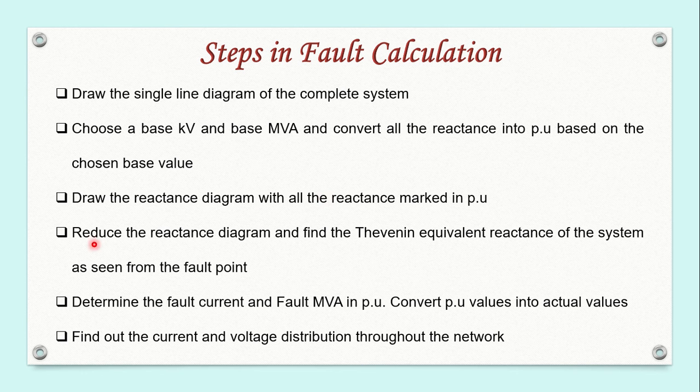And see step number 4. After drawing the reactance diagram, reduce the reactance diagram and find the Thevenin equivalent reactance of the system as seen from the fault point.